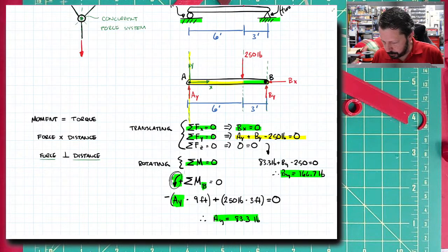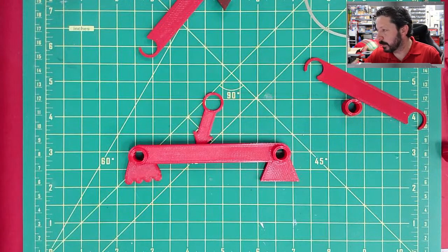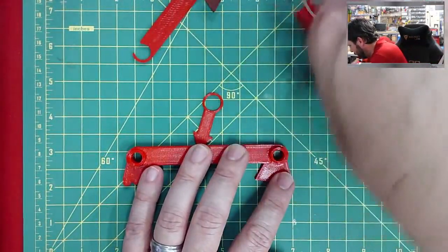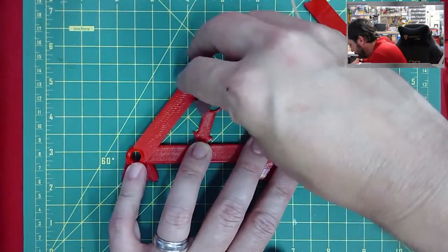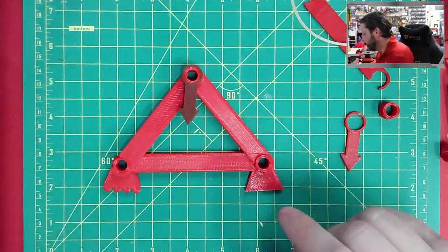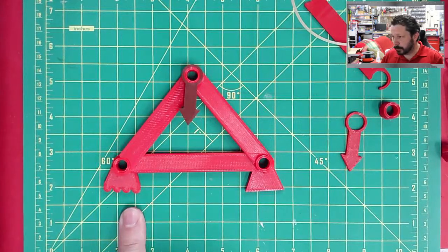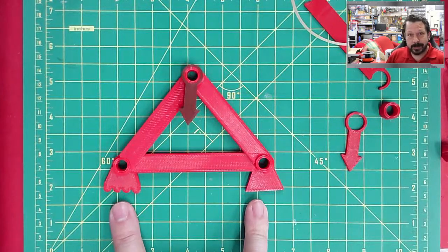So let's go into our truss. Let's rebuild our truss over here. This is the simplest truss that we could create, one that just has one force on it somewhere. Remember, the force has to be at a joint. And 2 supports of some sort, so a pin and a roller. Why do we use a roller, why not just 2 pins? That's more of a practical thing.